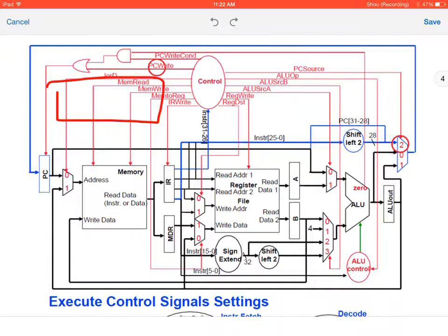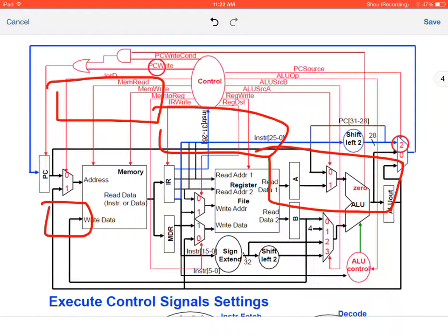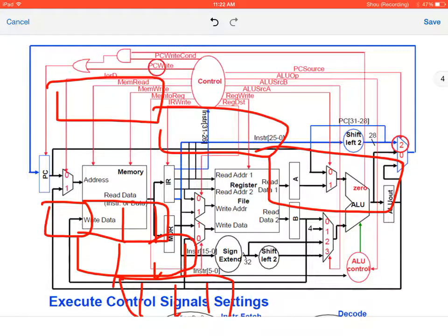Single cycle, you have your 5 stages and all of them have to be the same length, right? In pipelining, you have your 5 stages, but they're broken up. But it requires significant overhead. You have to worry about control hazards, data hazards, structural hazards. You have to have your hazard detection unit. You have to have a lot of buffering in between the stages. So we're looking for some sort of compromise between those two. Can we speed it up, but reduce the area overhead?